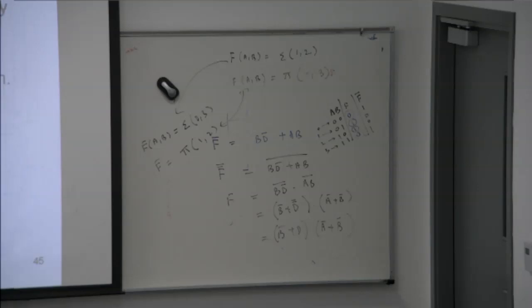Okay, the don't care condition can be used to help simplify the Boolean expression further in K-map. They could be chosen to be either 1 or 0, depending on which gives the simpler expression. I'll explain this with an example. Can you see here?